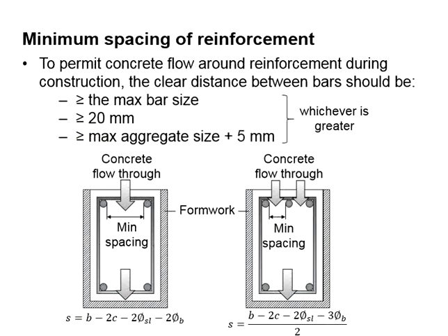Other than that, there are minimum spacing requirements for the reinforcement. This is not critical for the slab, as you know that the slab element has a relatively large section as compared to the reinforcement provided. The reinforcement provided in the slab is not likely to be congested.